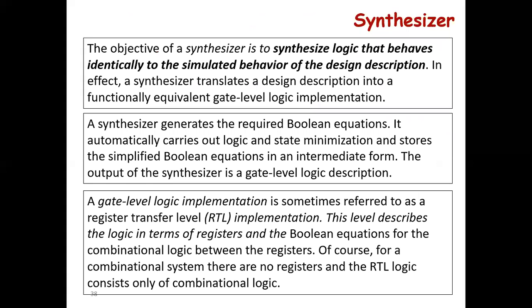So the main objective of the synthesizer is to synthesize logic that behaves identically to the simulated behavior of the design description. It translates a design description into a functionally equivalent gate level logic implementation, generates the required Boolean equations, automatically carries out logic and state minimization, and stores the simplified equations in an intermediate form.